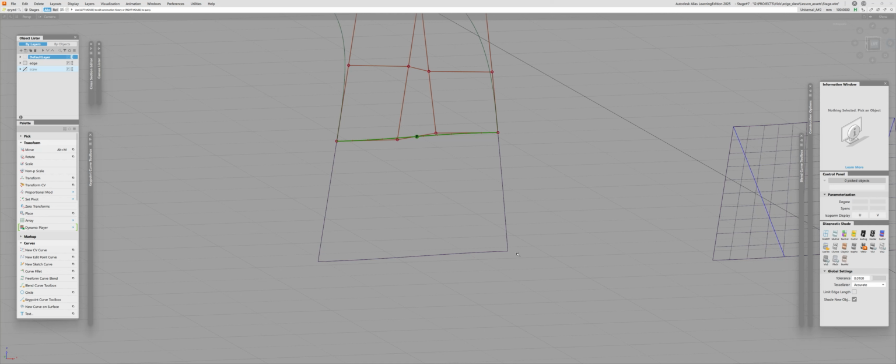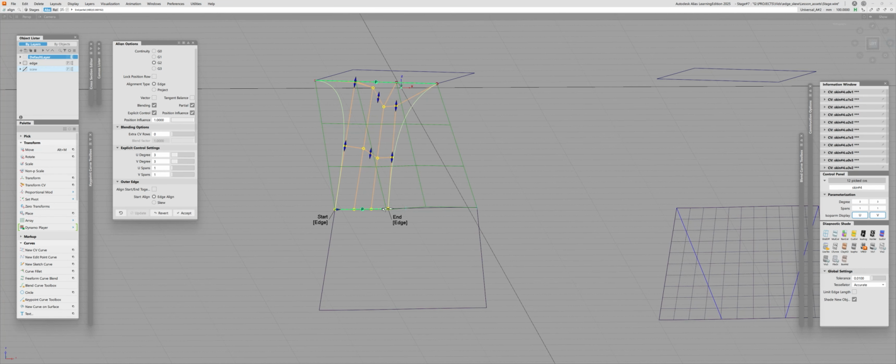Sorry, the align operation will happen, no problem. It still works how it's supposed to. If I cut the surface like this, for example, creating a hole or something like that, once again, it will work just fine. The problems will happen when the adjacent edge is trimmed, and not just a little bit, but completely chopped off. And it doesn't really matter which one. The edge align just stops working properly.